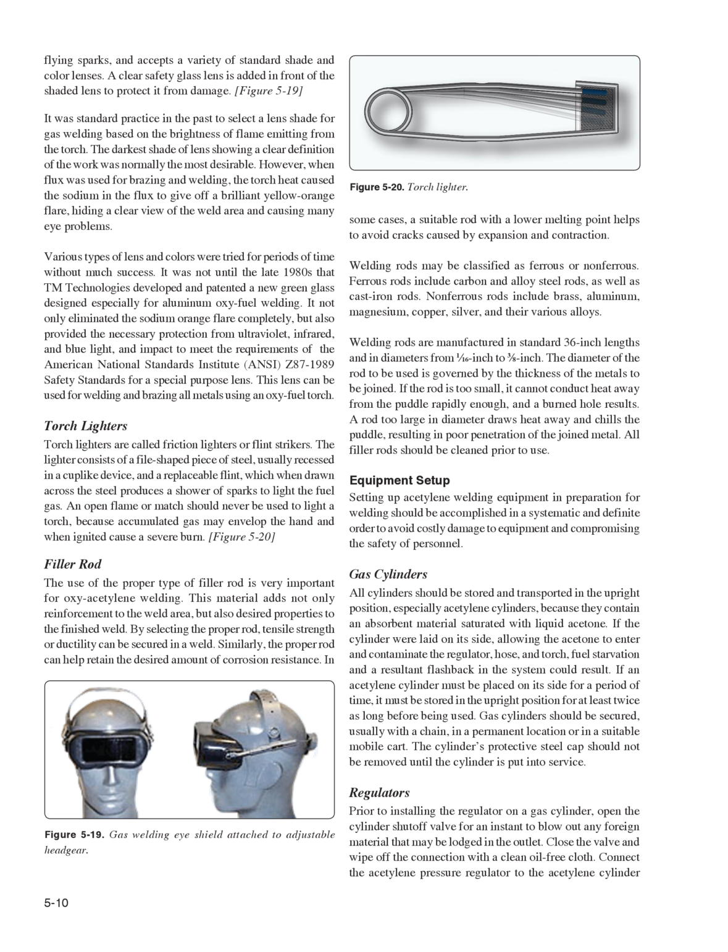It was not until the late 1980s that TM Technologies developed and patented a new green glass designed especially for aluminum oxy-fuel welding. It not only eliminated the sodium orange flare completely, but also provided the necessary protection from ultraviolet, infrared, and blue light, and impact to meet the requirements of the American National Standards Institute, ANSI, Z87 1989 safety standards for a special purpose lens. This lens can be used for welding and brazing all metals using an oxy-fuel torch.